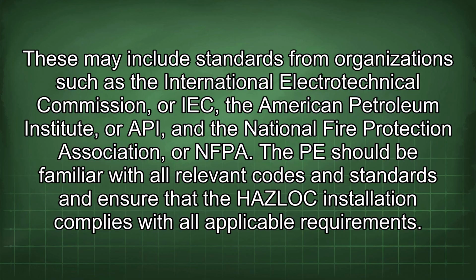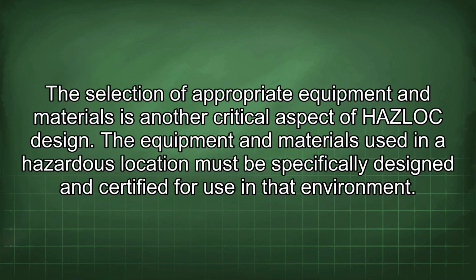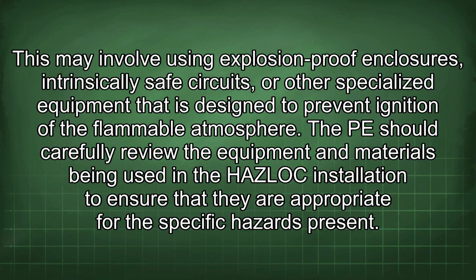applicable requirements. The selection of appropriate equipment and materials is another critical aspect of HAZLOC design. The equipment and materials used in a hazardous location must be specifically designed and certified for use in that environment. This may involve using explosion-proof enclosures, intrinsically safe circuits, or other specialized equipment that is designed to prevent ignition of the flammable atmosphere. The PE should carefully review the equipment and materials being used in the HAZLOC installation to ensure that they are appropriate for the specific hazards present.